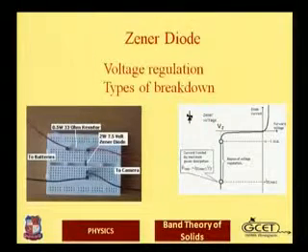With this excess kinetic energy, electrons move into the conduction band. When they collide with other atoms inside the PN junction, they release more kinetic energy and more electrons, and a multiplication process occurs. One electron breaks one bond, and as a result there are two electrons in the conduction band.